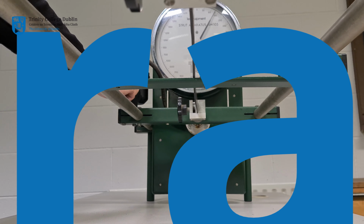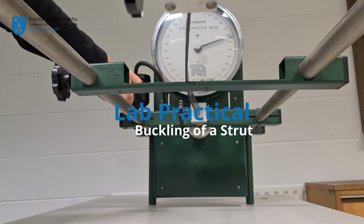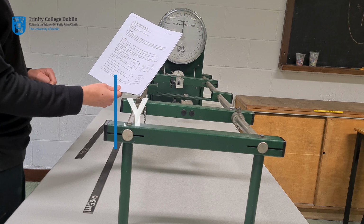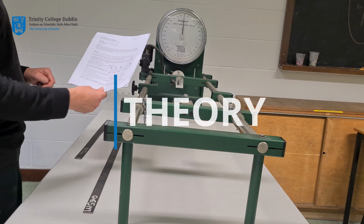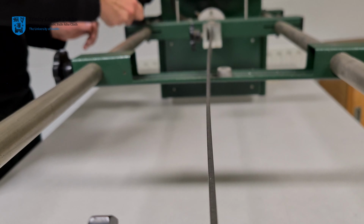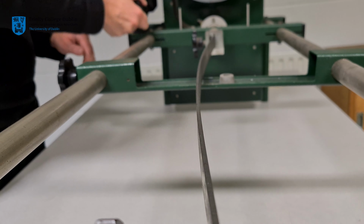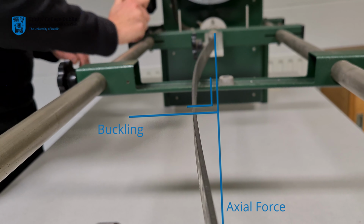2E4 Lab Practical B: Buckling of a strut. In this laboratory session, we will investigate the buckling of a number of struts with varying end conditions. Buckling is a form of sudden, large deformation experienced by a structure under compressive load. It occurs normal to the direction of application of the load.